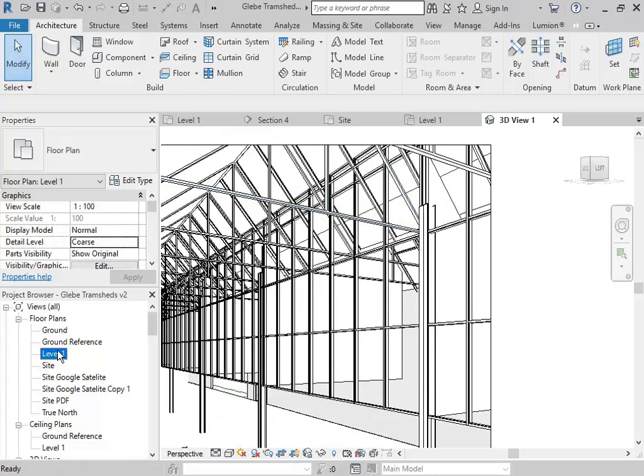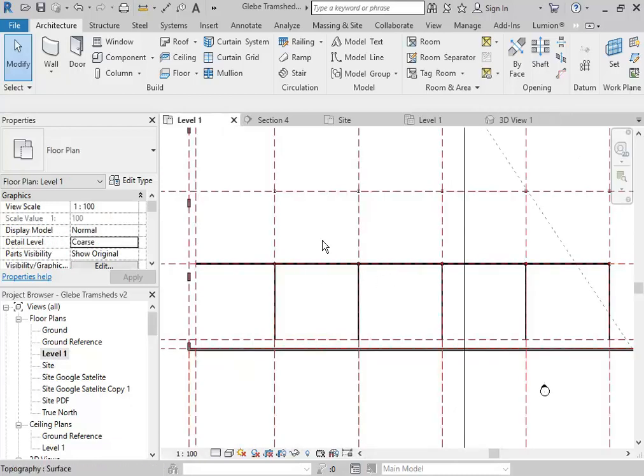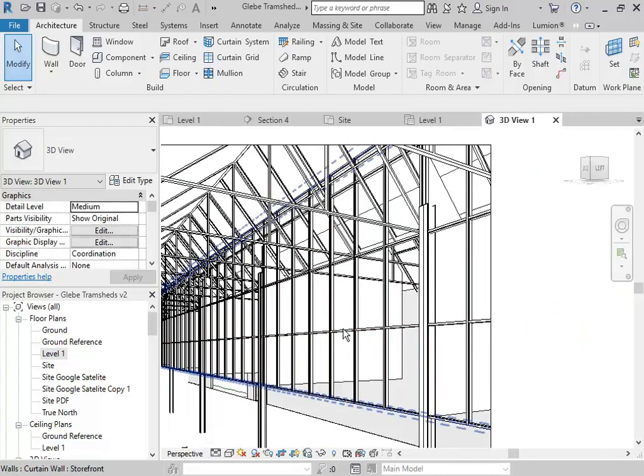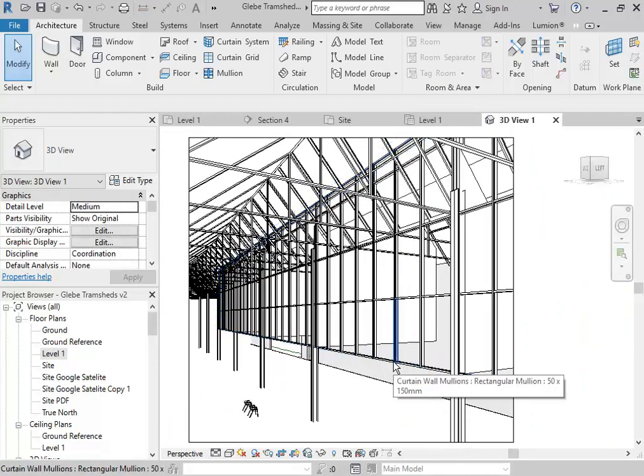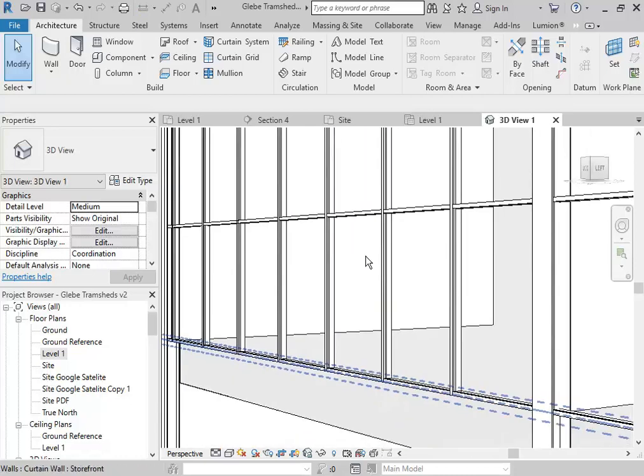So if you want to put a door in a curtain wall panel, you can. It's just different to a normal door. There were videos about it. Of course. So what you do, firstly, you need to set the grid to the size of what the opening is to be.